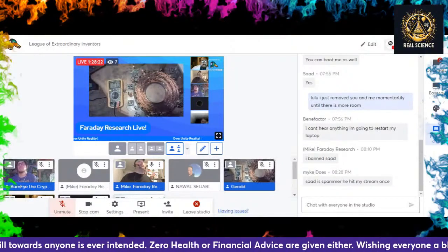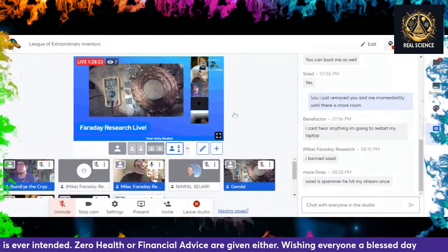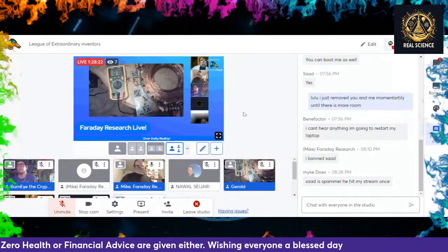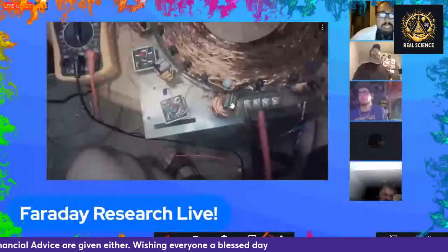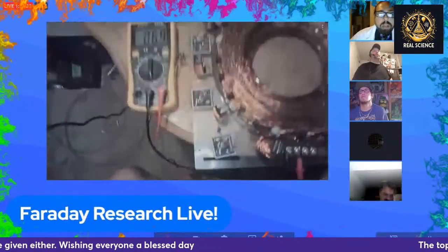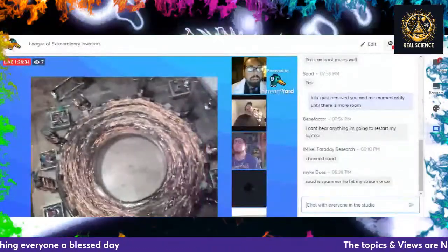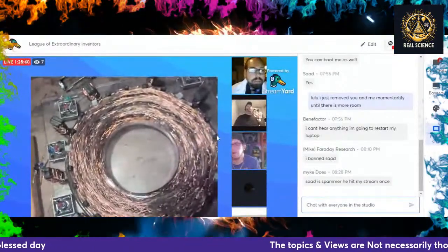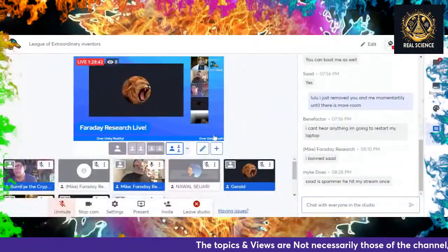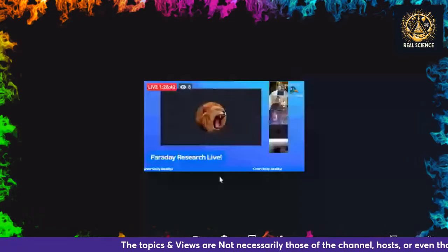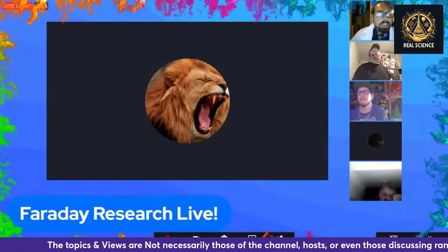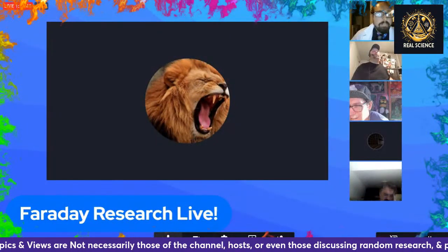Yeah, so using a thinner gauge winding is not going to be a problem, you can step up the voltage safely. Okay. Yeah, maybe the next frame that I wind will be a thinner wire. The power supply doesn't need to be a high amp power supply, but it needs to have the high voltage. Like you could use a low amp rated variac and put a diode on it to get your high voltage.